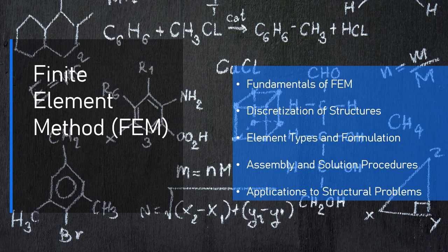Benefits: coupled thermal mechanical analysis allows the simulation of both thermal effects and their impact on mechanical behavior. Accounts for nonlinear material properties, thermal expansion coefficient, and temperature-dependent material properties. Can model non-uniform temperature distributions, such as those from external sources or internal heat generation.